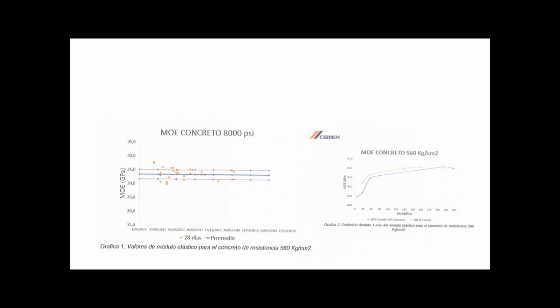What we have here is part of the quality control that was involved in Atrial, and as I said, we had to stay within a range of the modulus of elasticity so that we could ensure that in fact the movements were predictable. This chart shows the measurement of the modulus versus the construction periods that we were working on. Over periods of the construction, we would take samples of the concrete, measure the modulus of elasticity, and hope to stay within that zone.